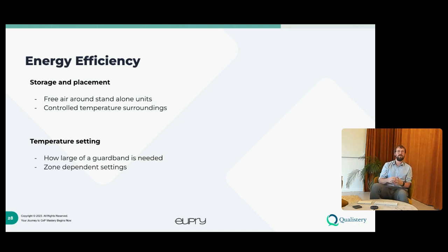And the last part I want to mention has to do with zone-dependent settings. It's something that we see in warehouses, where often large HVAC systems have the possibility to be zone dependent, so that areas of the facility that are not close to doors and gates, as an example, can be less delicately controlled, which would often mean that the cooling systems would have to run for shorter or longer periods of time, but further spaced. That would give a lower stability, but often it has very little impact on product stability.